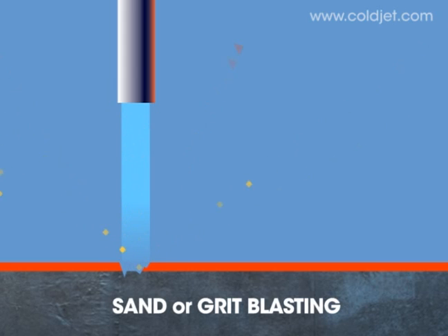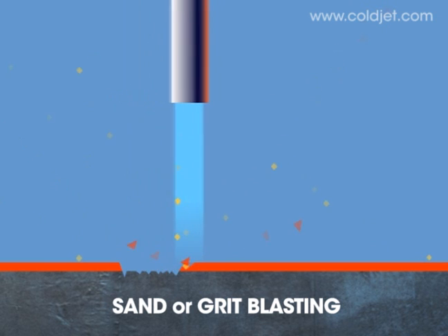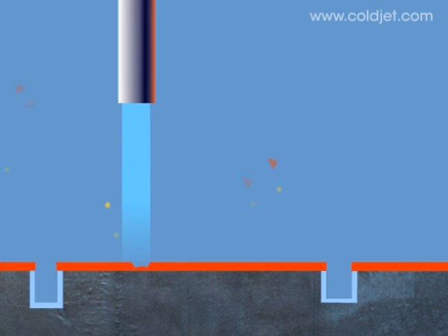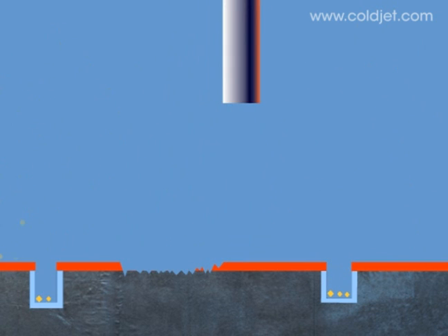Although it effectively removes surface contaminants, it also picks away at the substrate, wearing it away over time, altering surface geometries, destroying critical tolerances. Sand particles can also become entrapped, causing critical problems that can shut down the manufacturing process while the problem is solved.